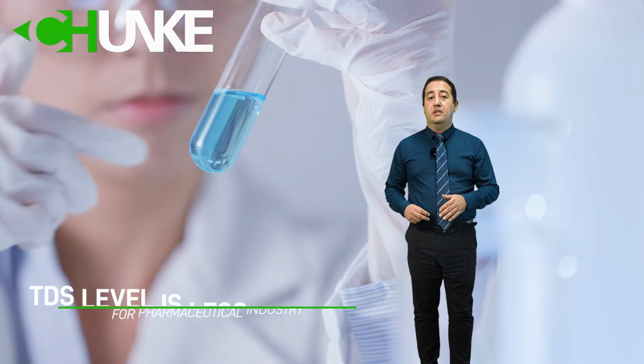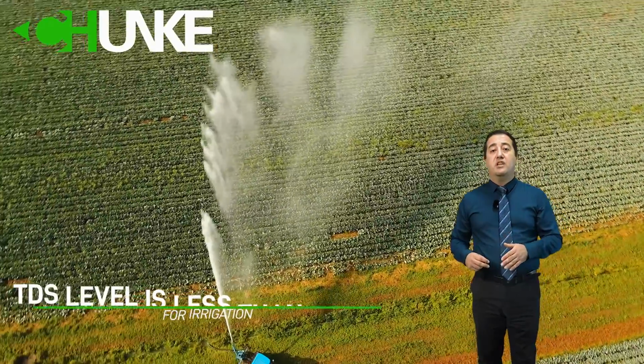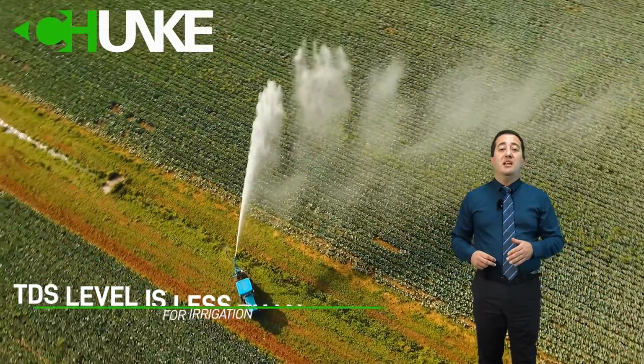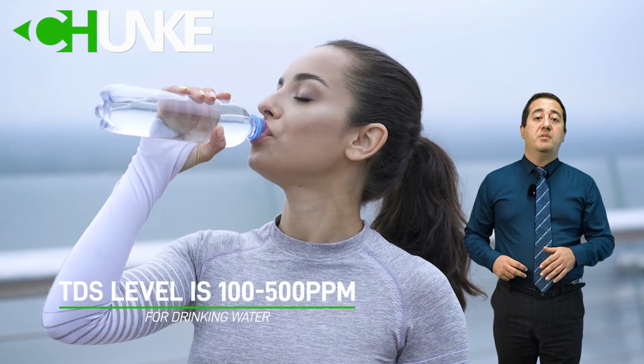As regards to your application, consider which TDS level you want to achieve for treated water. For example, if you use treated water for the pharmaceutical industry, TDS level must be less than 1 ppm. If it's for irrigation, TDS level must be less than 500 ppm. If it's for drinking, TDS level must be around 100 to 500 ppm.